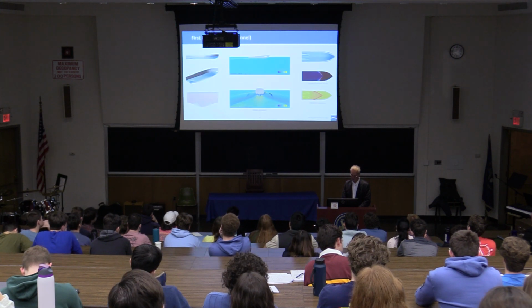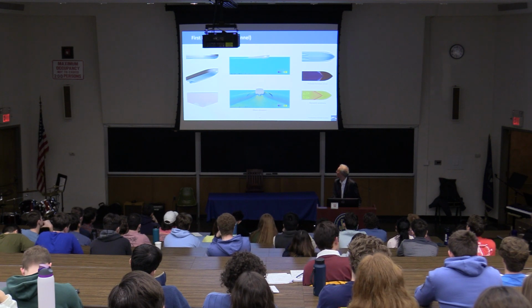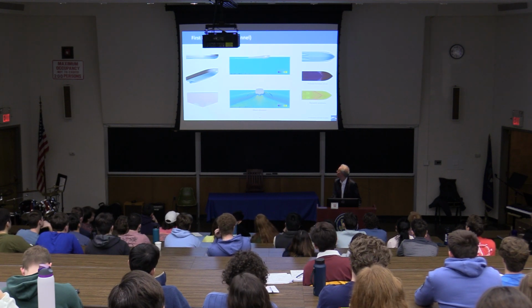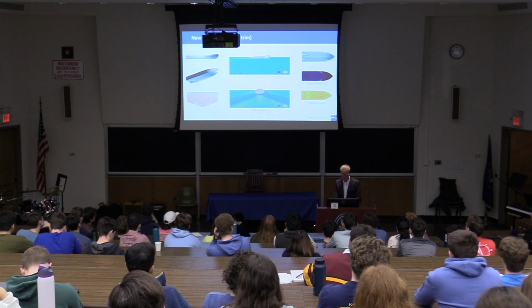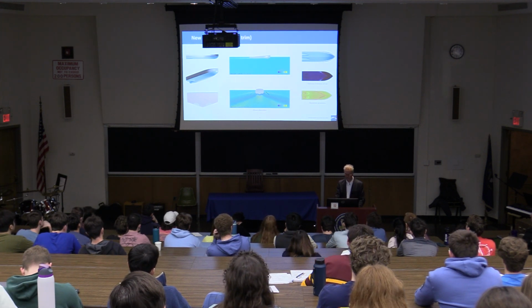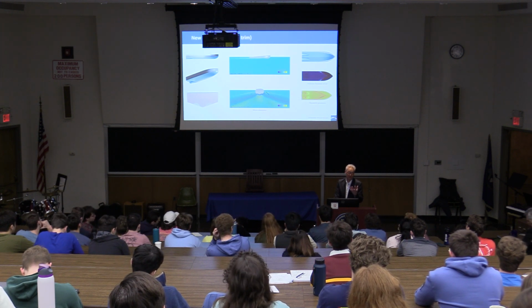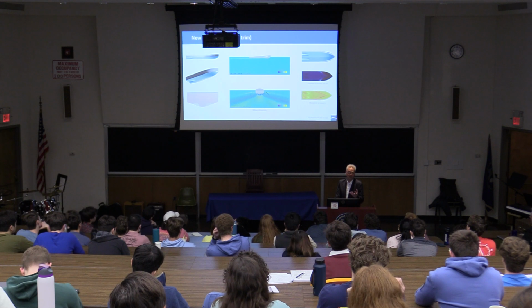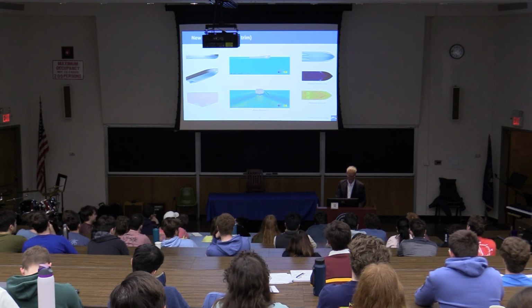Let's take a look at flow fields and at the designs. That was the design we started out from. That was the actual baseline from which the optimization started. So there were some manual improvements. I'm not saying that you would not be able to do manual improvements up front. Don't start with a box and hope to get a nice hull form. You want to start with something that's already pretty decent.